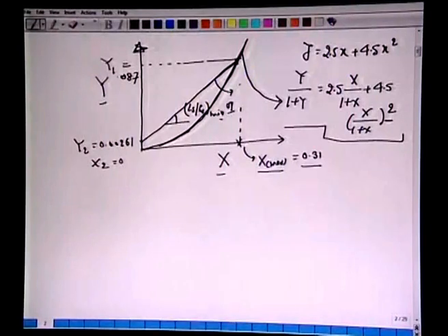But if you plot it carefully on a graph, you should get this result immediately. The point where this LS by GS minimum curve intersects with equilibrium will give us X max as 0.31. Okay. So from here, the slope LS by GS minimum we can obtain. If we know this slope, I leave this as an exercise, one can obtain LS prime.